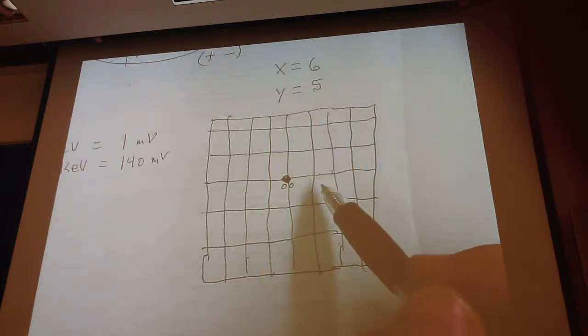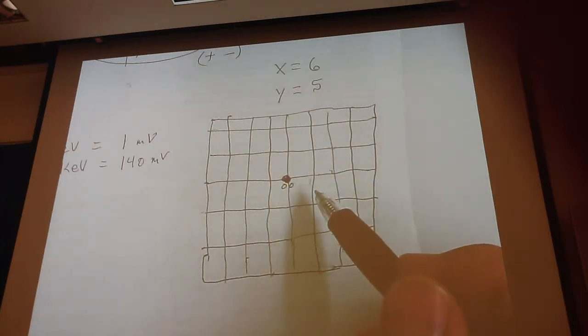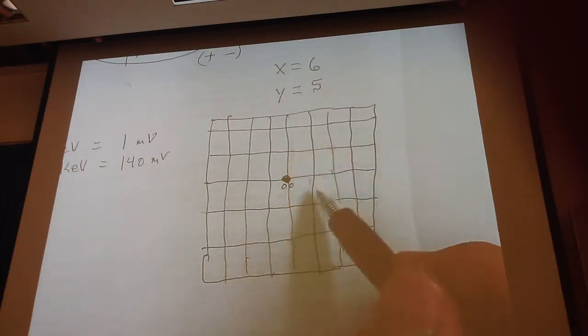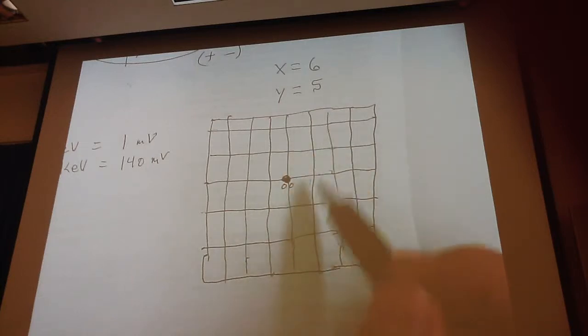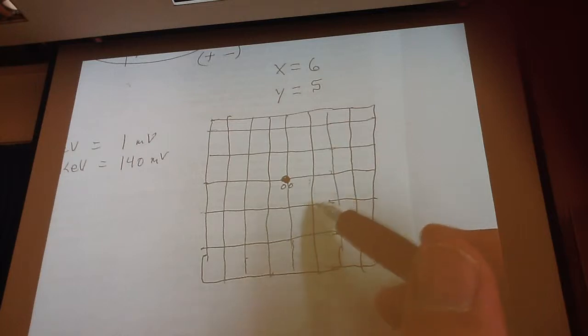Okay, anytime we send a voltage pulse through silicon, it has the capability of storing it, like a little capacitor. Okay, and if I constantly refresh that by continuously sending pulses through it, then that charge remains and the computer knows that there's information there. Okay?